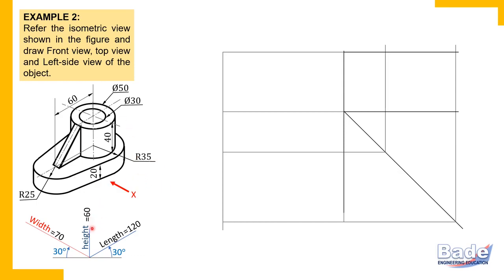Okay, but try to understand here. Bottom features and top features are not identical or the same. That means the lower side and upper side are not the same. Right side and left side: the left side is a curved edge, the right side is also a curved edge, but these edges have different radii. So the left end and right end are also not similar. But all visible features on front and back appear the same. So front and back are similar. Front side and back side are similar, like mirror images.